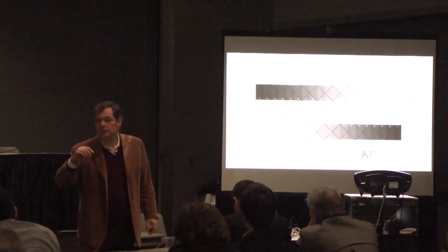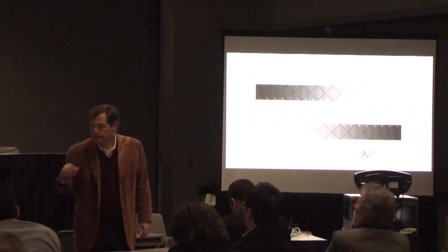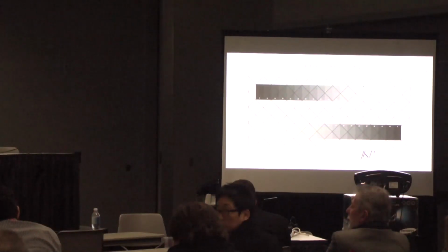I have one question. How precise do you think your value of ghosting is when you look at your screen? I'm sorry, I'm not hearing the question. Can you repeat the question, please? I was just asking myself how precise your ghosting value is, because what you have here is the value based on the input value. But all the processing down to the screen, gamma being one of those, may change these percentage values. So you read ghosting is maybe 5%, but it's based on the input value, not on the screen value.